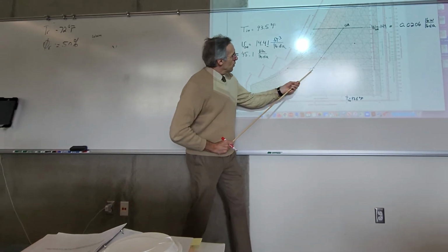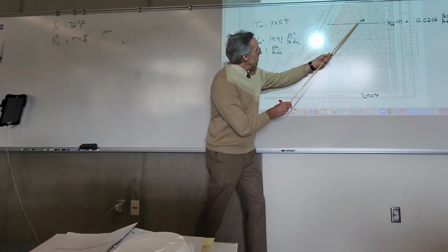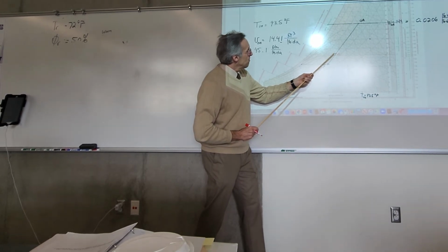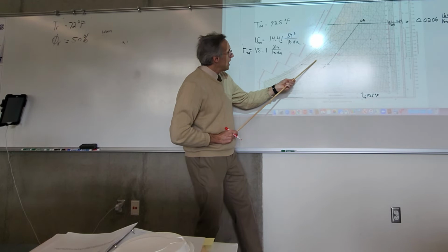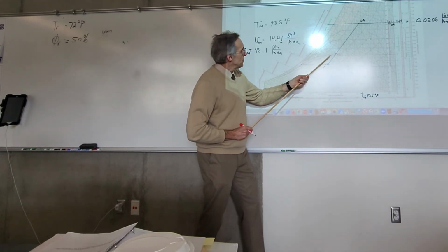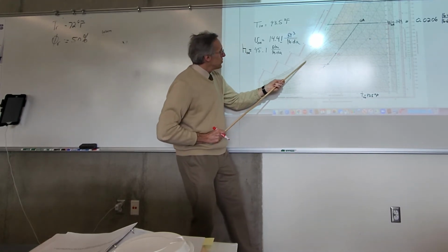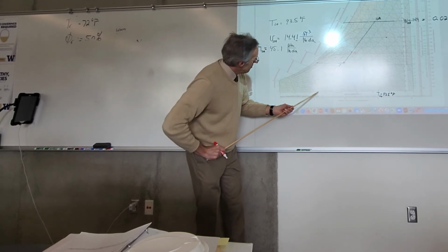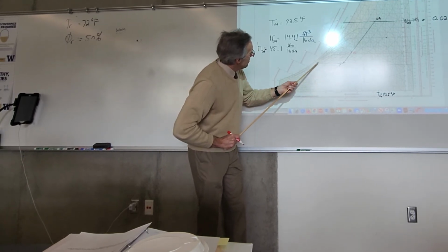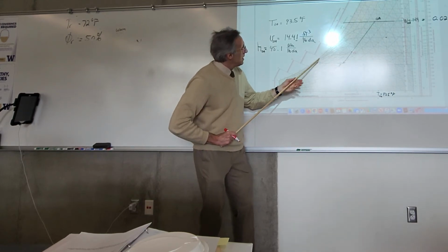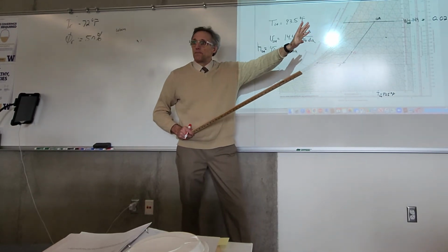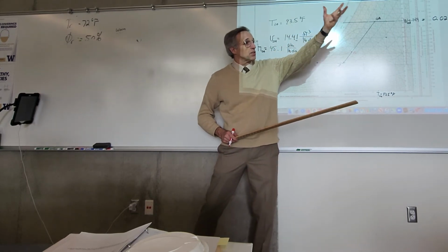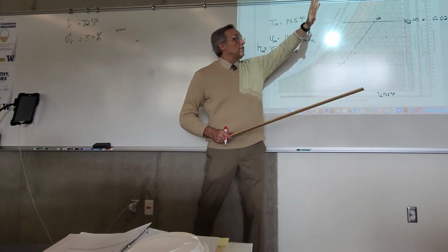Okay, so we would bring return air, mix it with outdoor air, producing a state M, which is mixed air, and then the mixed air would go through the conditioning unit, and that would be our air conditioner right there. That's our conditioning unit, bringing us to a nice cool 55.5 degrees and 90% relative humidity, and then that would dump into our room. So you put your hand up by the vent, or the grill that's pushing the air in, and you'll feel 55 degrees.